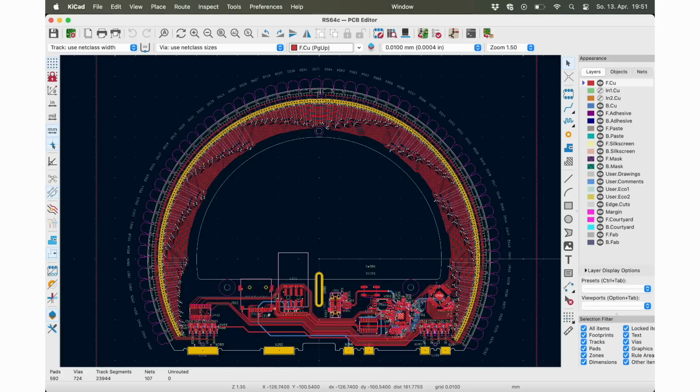Under these conditions, the PCB behaves like a waveguide. That means you have to consider not only the forward path of the signals, but also their return path, which must run in parallel to the outgoing signal lines. If this is ignored, the edges of the signals will become distorted. Crosstalk between the signal lines will increase, and electromagnetic interference, EMI, can become a serious issue. To avoid these problems, the design includes dedicated grounding planes.